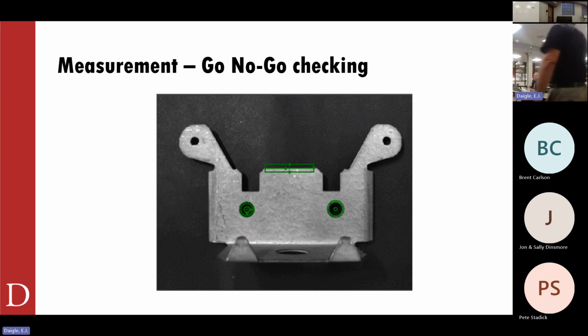I've seen people, and this isn't the way to do it, take a 6-inch steel rule and put it under the camera and calibrate to units that way. That's a quick way you can get it up and running. But then you do need some sort of calibration grid under there, so you are actually calibrating to the units that you want.